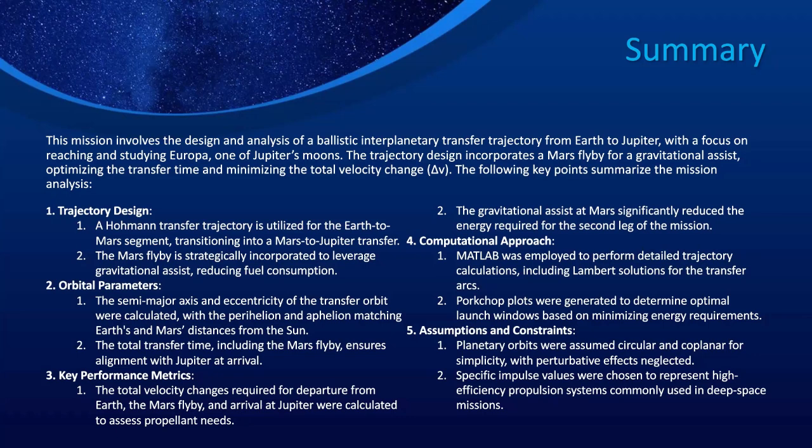It was employed to perform almost all of the calculations. The only thing that we got elsewhere, I believe, was the NASA website, in order to get the C3 versus mass graph, and that will be shown also in the appendix. And the pork chop plots were also generated in MATLAB in order to get the time of flight, the C3, and the launch date that we actually needed.